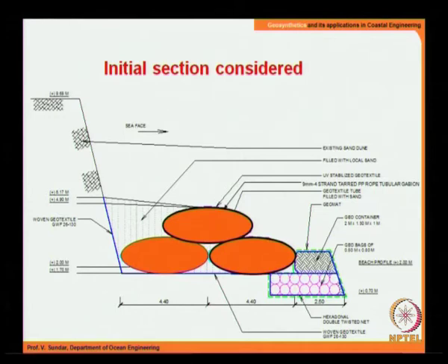In the event that it is completely submerged below the water, you do not have this problem. But when it is exposed to the sunlight, there is no guarantee for how many years the geosynthetic products can sustain in weather like what we have here, for example around 40s during summers. So the sustainability during this period is extremely important.